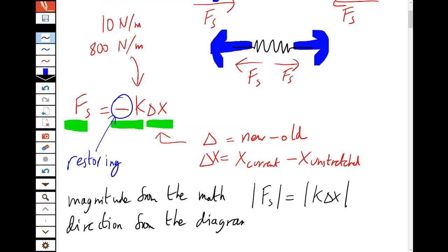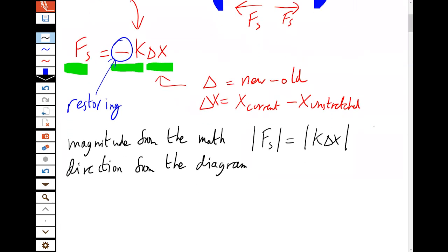Like, it is possible to keep all the pluses and minuses consistent and work them all out, but there's no points for showing off. Like, if I have a beam squeezing a spring down, and I'm told that beam is compressing the spring, well, I know if the spring is being made shorter, then the force is up. So I don't have to go through all of that.